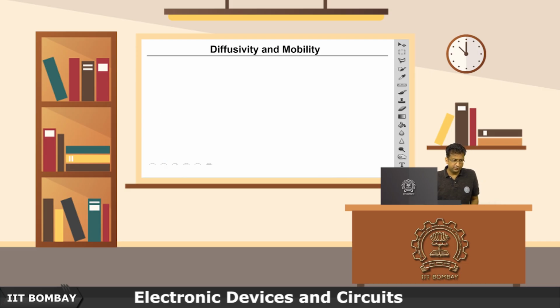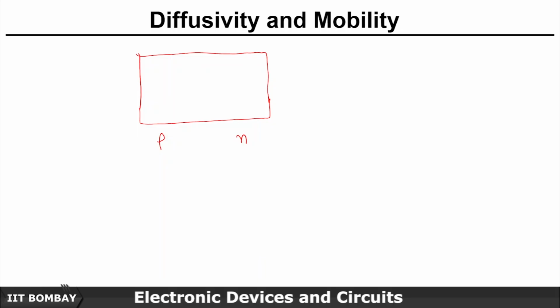Let's discuss the case of a PN junction. Actually, we will be talking about the PN junction in later lectures in detail. But let's talk about it just to understand where this electric field is coming from, from the balance of diffusion and drift current. Let's say these are my two semiconductors, P and N. Why am I taking the case of a PN junction? Because I want to take an extreme case where a concentration gradient is there. Let's say this is the metallurgical junction.